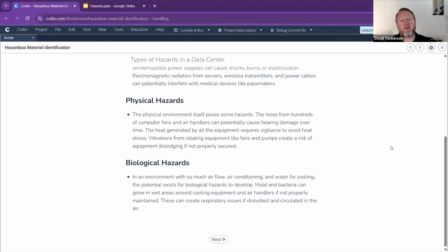HVAC systems are kind of an improvement on the standard air conditioning. Legionnaires' basically grows in the still water that happens to appear in a lot of air conditioning systems. It grows as a bacteria, then gets kicked around, recirculated into the air, and you breathe it into your lungs. HVAC allows it to clear that out, and it should, touch wood, be looking after all that. But again, this is another hazard that we need to be aware of.